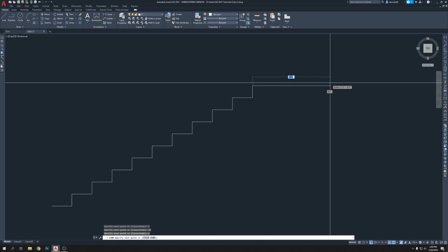The standard landing is let's say 4 feet 5-6 inch, and we're going to make it 5 feet. This is the place where we're going to use the 5 feet. We can do it two different ways. One is I can press 5 and press the feet button, which is next to the enter key, which is here. If you want inch, then you need to hold the shift key and press the same button. So let's say this is 5 feet.